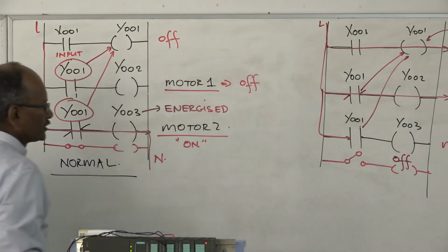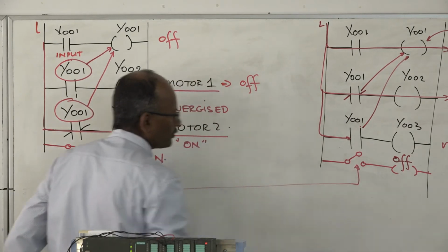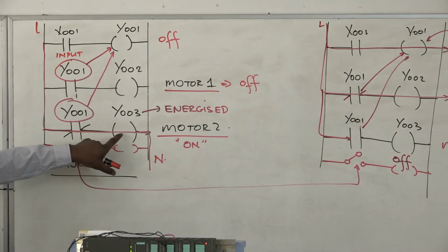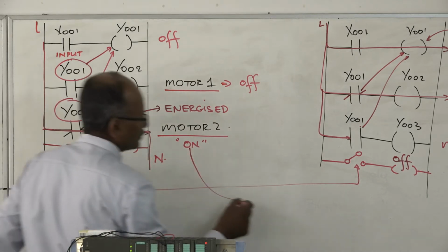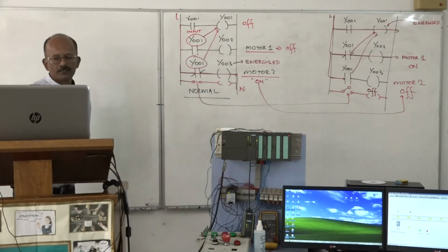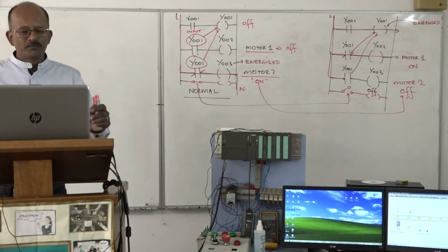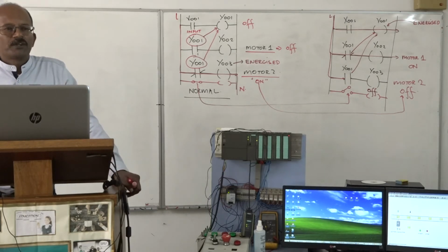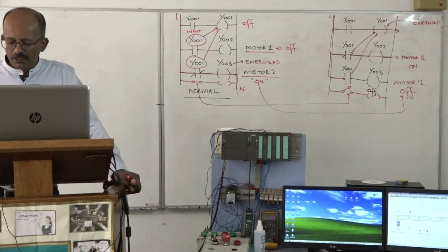So it went from normally closed to normally open, and I can see here that Y003 would then go from on to off. So in pencil, don't hesitate to use your electrical circuit symbols when you are asked to interpret ladder diagrams.